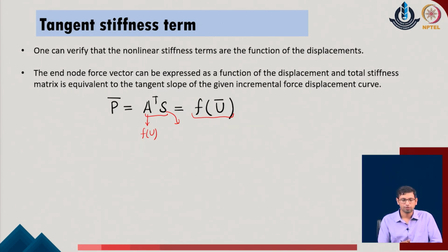So, if the overall forces or the nodal forces of the system are expressed already in terms of the nodal displacements, we can simply define the change in this parameter with respect to these nodal displacements as del f upon, so I can write it not as a partial derivative, but dp bar upon du bar, the standard value of the derivative with respect to the nodal displacements of the given system.